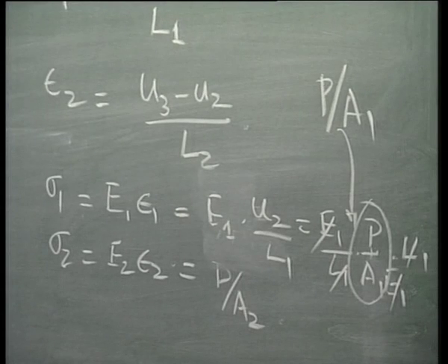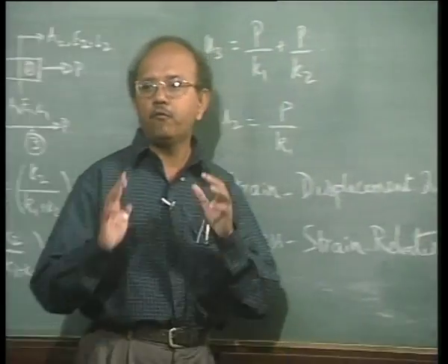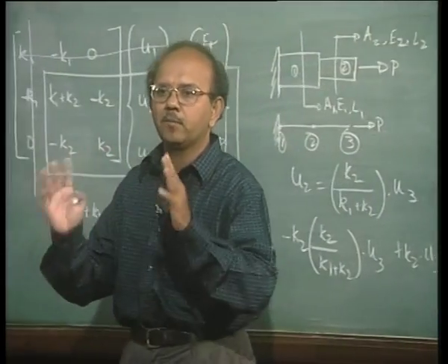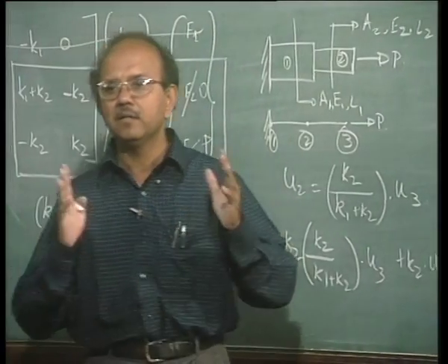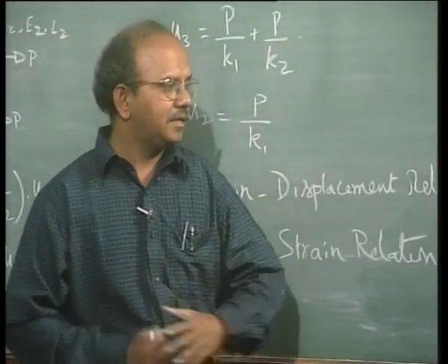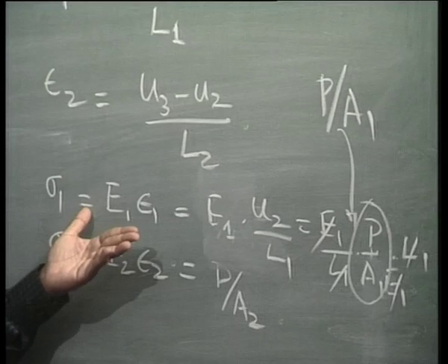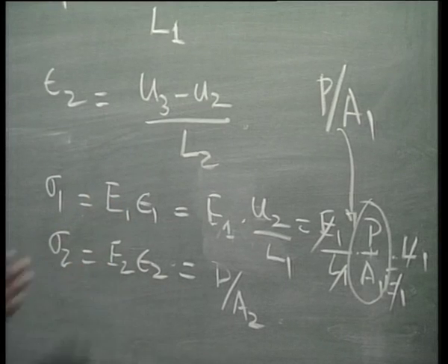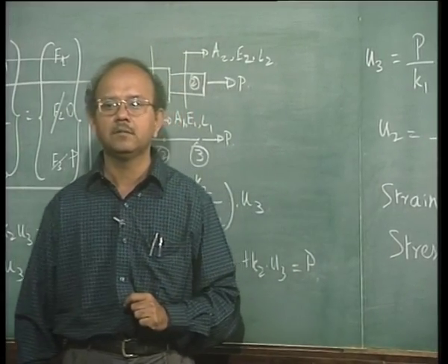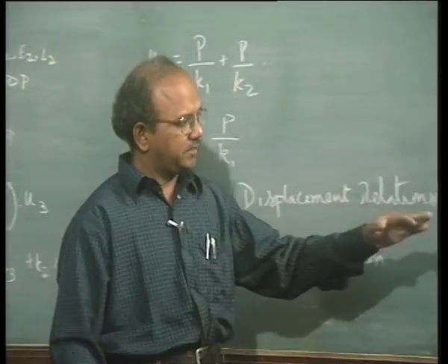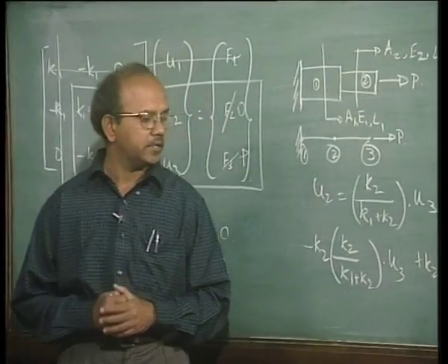Stresses develop due to internal forces, and in one hand they are nothing but an equilibrium equation. So, whatever be the material, when I apply a force, this force has to be equilibrated by the internal stresses, and when these internal stresses develop, they develop in such a fashion that they are independent of E1 and E2. So, that is a very important thing to realize, because people usually make a mistake, and that is why I have pointed out this particular case.